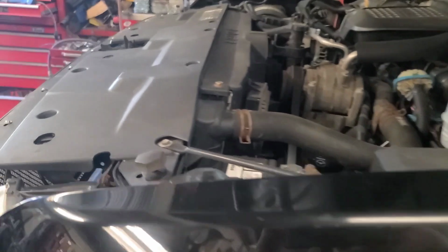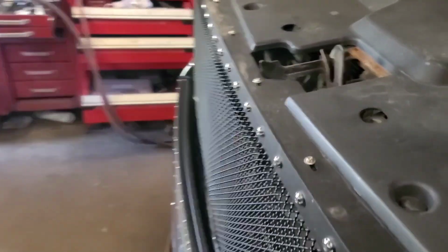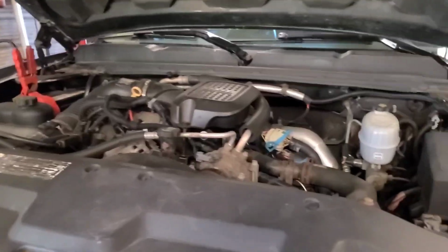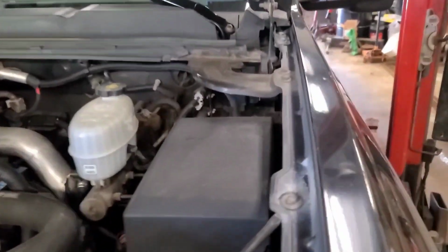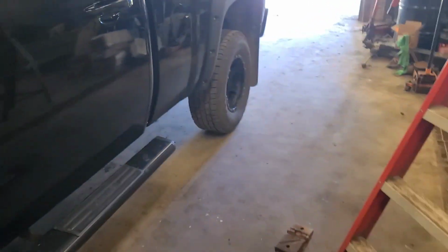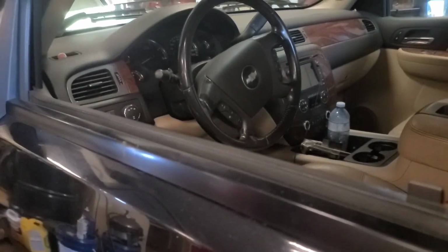Well, good morning, viewers. Today we have a 2008 Chevrolet Silverado 2500 HD with the 6.6 Duramax. It's here because the trailer brake control module has apparently failed. It has no communication with the rest of the network. Somebody's installed a used one, and we're going to try to program it to the vehicle today. So I'm going to do a network scan first off.